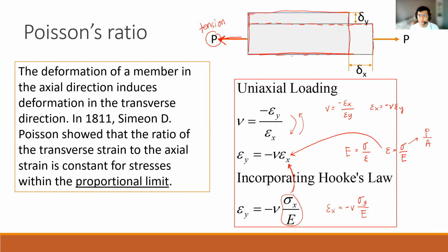So elongation, I think the formula for that one is the strain is equal to the elongation, or the deformation rather, divided by the total length. It's the other definition of strain, di ba? So strain is the deformation all over the total length. You can also do this if the problem is asking for further refinement of the details. For example, what would be the total length if the strain is limited to this particular number? What would be the deformation if the length is only this long, di ba? It will depend on the situation that you will be having.